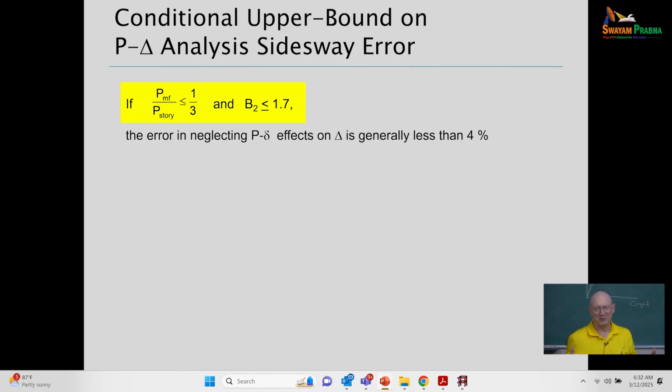Where would he have a design with a steel framing where this is larger than 1/3? Why? Moment connections are expensive, and you're typically going to have a lot of your connections of floor framing to your columns as basically web type connections that don't transfer significant moment. We idealize as pins for the analysis.